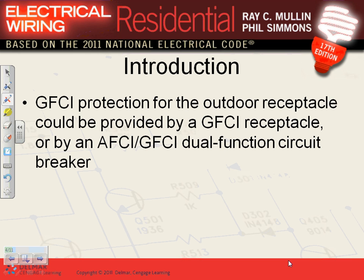The second thing also, the hallway has to be what? What does the hallway need to be? Arc fault circuit interrupter. So the hallway has to be arc fault circuit interrupter. So this circuit breaker that you have to be GFCI/AFCI or just AFCI, and the receptacle outdoor has to be GFCI. So keep in mind GFCI, AFCI.